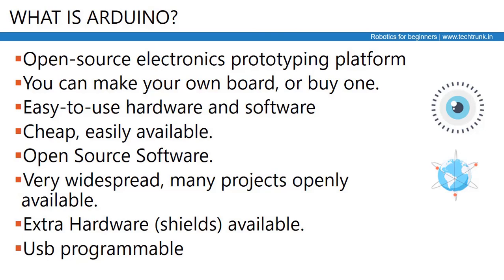Arduino boards are widespread and many projects are openly available on Arduinos. And extra hardware shields are available. Means, in case you want to interface other devices like Ethernet, memory card, GPS, GSM, you don't need to worry about the interfacing circuit for interfacing that particular module with Arduino, because shields for interfacing those sorts of devices with Arduino are readily available in the market. So development is very easy with Arduino. One of the best parts is that it is USB programmable. You don't need any separate programmer for programming Arduinos. It's very easily programmable using a USB type 2 cable.